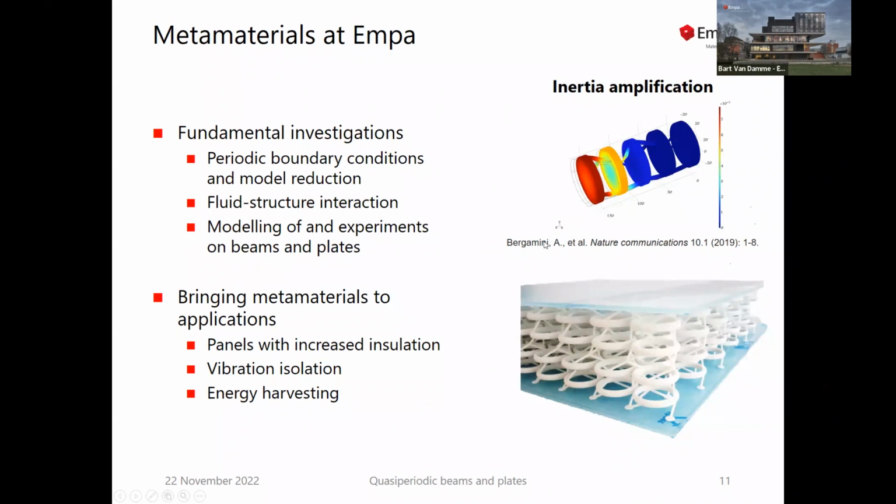Especially Andrea Bergamini has been working on waveguides, metamaterials that rely on inertia amplification. It means that the masses in our mass and spring chain here don't only move up and down, but we couple this up and down motion with a rotational motion due to these diagonal struts here. And because of this combination of translation and rotation, we can increase the perceived dynamic inertia of these disks and therefore reach low frequency band gaps.